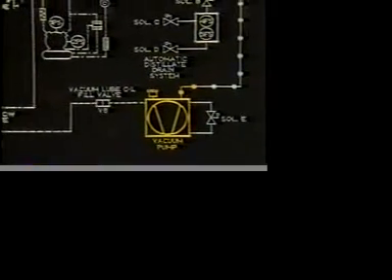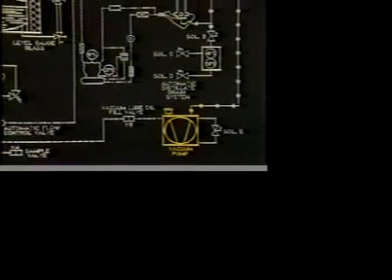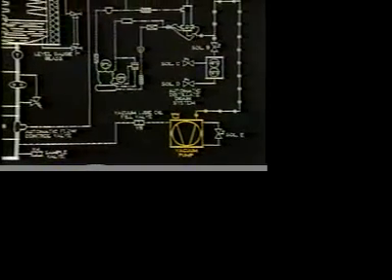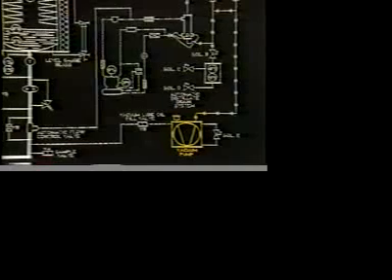The only other thing to be mentioned is that the non-condensables will go through the vacuum pump, and we now have the option, after they leave the vacuum pump, to put them into a flare system, a collecting system perhaps made of charcoal filter material, or in some cases we may opt to send these non-condensables directly back to the atmosphere. And that pretty much completes a review of a typical schematic.